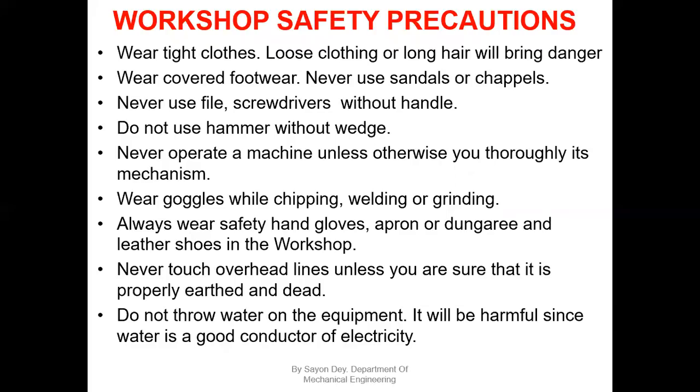Okay, next, workshop safety practices. Basically, we have to be careful in our workshops, because in case of welding, an accident may happen anytime. So there are some restrictions, like we have to wear covered shoes. We must not wear loose garments. Every point is also written here.